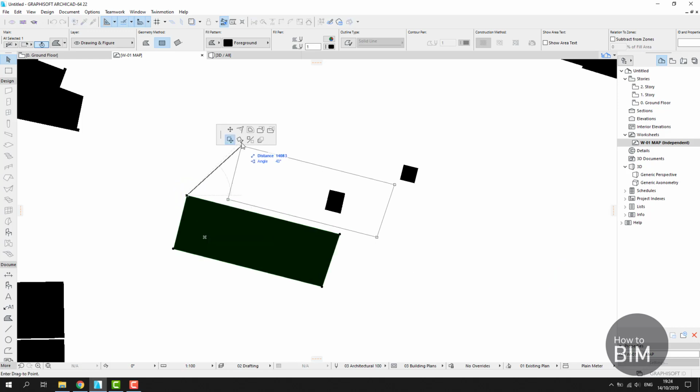Okay, next one is rotate, and rotate is also something that you should learn by heart, and for that I need to check a paper, and it's Ctrl E. As I told you at the class, I set up different keyboard shortcuts for Archicad, so for the sake of this tutorial I try to work with the ones that are preset, but if you're gonna work with the program for a long time, and if you're gonna work also with different types of programs, you will maybe change this.